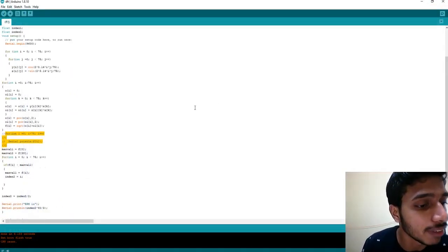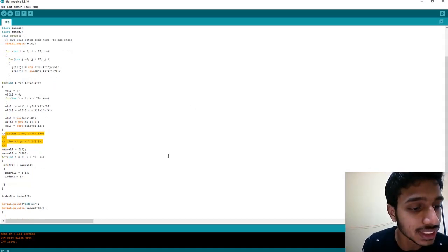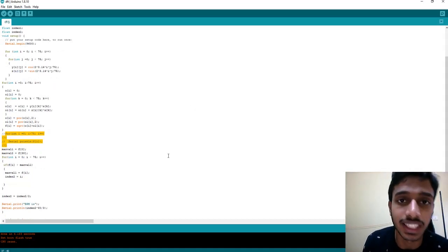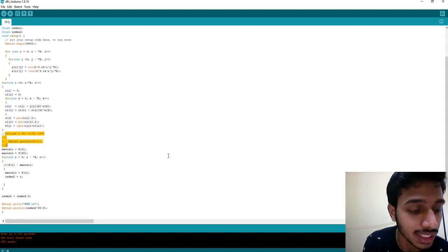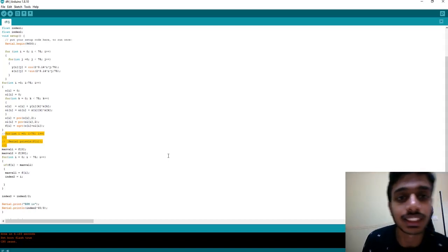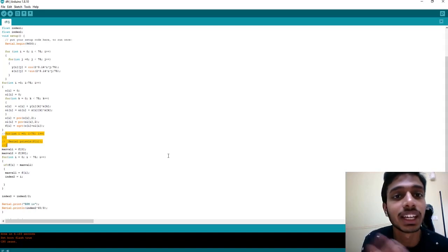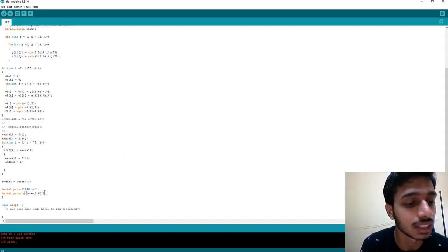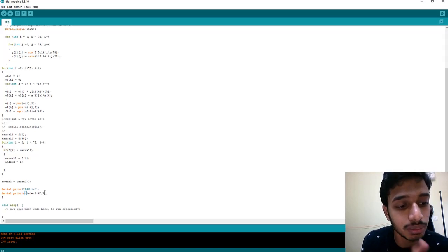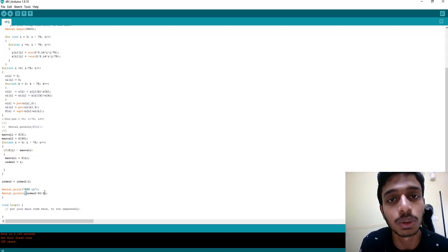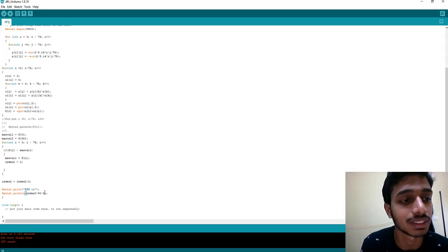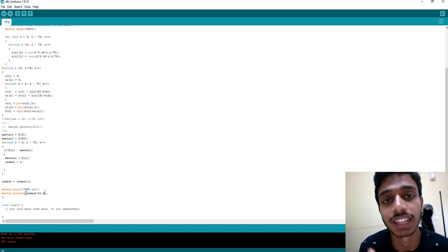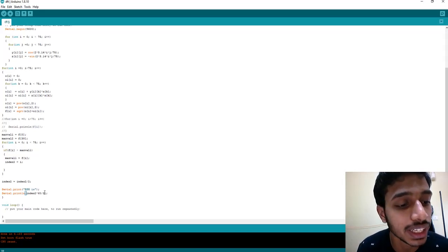So we find the indices of those peaks, and from the index obtained from the first peak, we convert that index into frequency again and multiply it with 60 in order to get the beats per minute. That is what we do here. I divided by 3 because the formula is BPM equals 60 into index into Fs, that is sampling frequency, divided by length. Here Fs is 25 and length is 75. So I divided by 3.